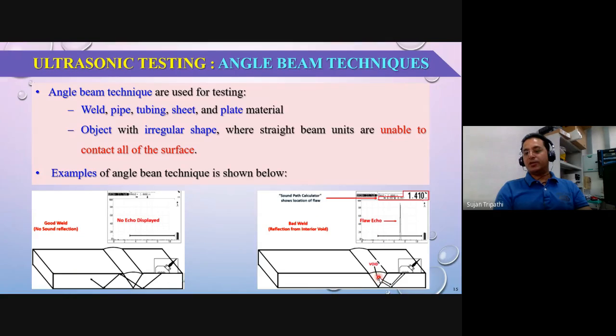If you see the second figure, you can see defects. Small voids are here, and if we produce the wave beams, they go to the void, and return from the void surface to the original surface, where the receivers are, and that helps to show the defects in the monitor, right?